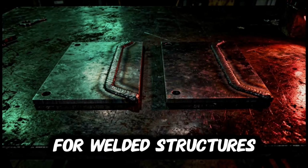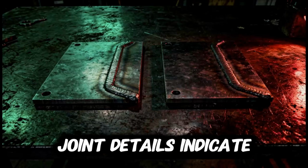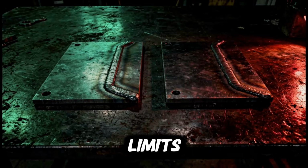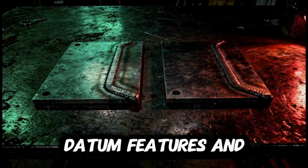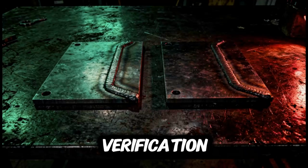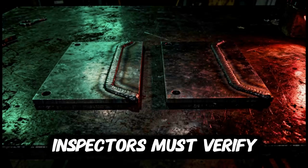For welded structures, weld symbols and joint details indicate expected profiles and acceptable reinforcement limits. For machined components, datum features and geometric dimensioning tolerances guide alignment verification. Inspectors must verify that drawings are current revisions and that any engineering change orders have been incorporated.